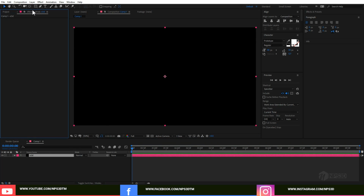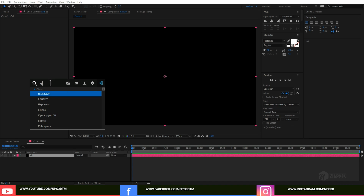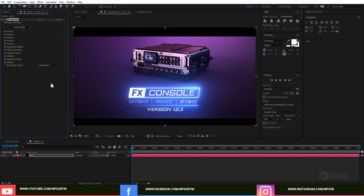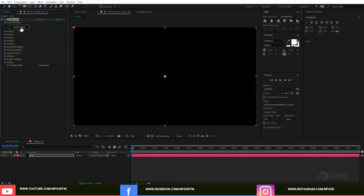So select the layer and press Ctrl space bar to bring out the FX Console. But if you don't have this plugin, you can also go to the Effect and Controls panel and just type Animating 3D. But I have it, it's 100% free. It's also from Andrew Kramer's Video Copilot. You can go to www.videocopilot.net and search for the VC Utility plugin FX Console. So let's go inside the scene setup.